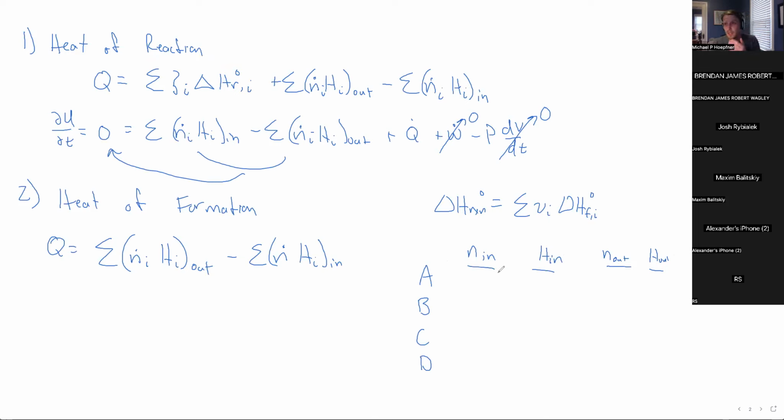So in the first exam, we talked about balancing reacting systems. So we're going to have numbers for the flow rate in and out of all of these different chemical species. Then in order to do the energy balance component, we need to find enthalpy values for each of the reactants and products in and out. Now, most all chemical reactions on an industrial scale are going to be partial reactions, and that's why we have the reactor separator, so we can recycle back all of the unreacted material.